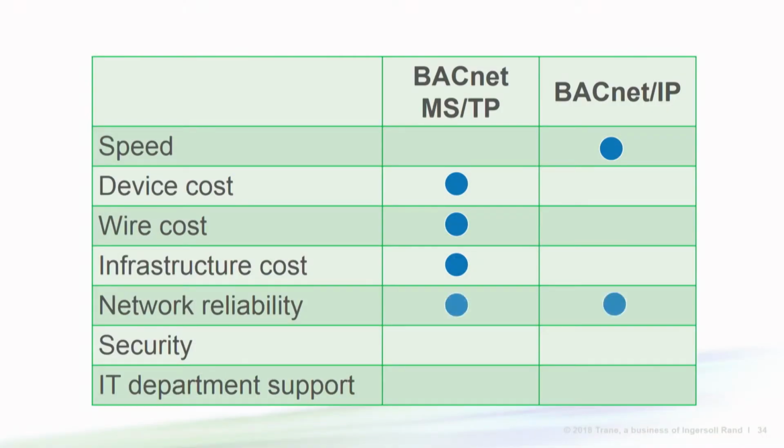But because the building controller uses a web browser interface, I won't be able to monitor the building remotely. However, if the VAV boxes are connected with Ethernet IP and the network goes down, the building controller can't communicate with the equipment controllers. So there is no system-level control and no way to monitor the building. For this one, it's hard to pick a definitive winner. So let's just give each protocol a check.